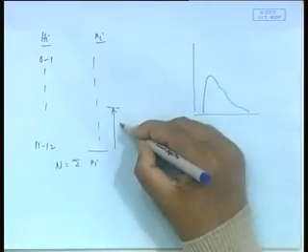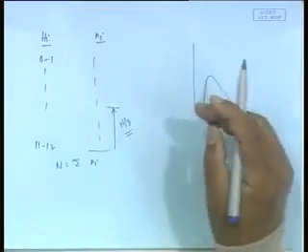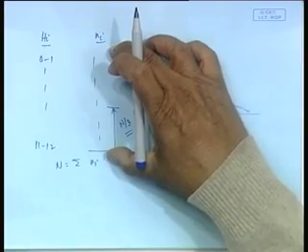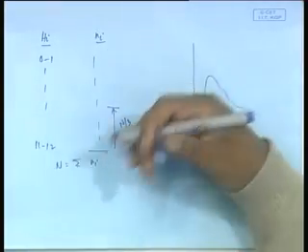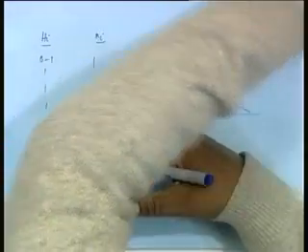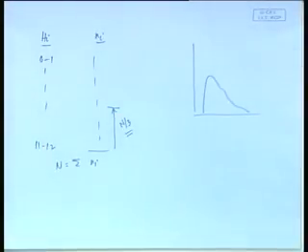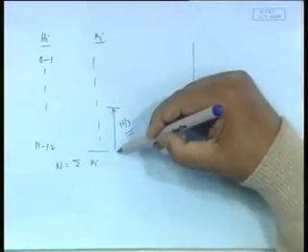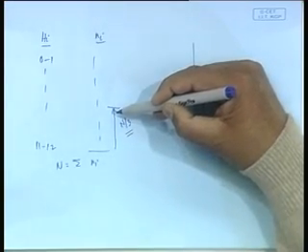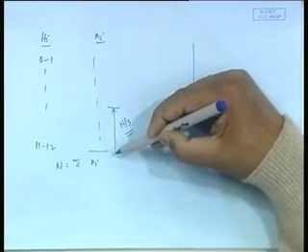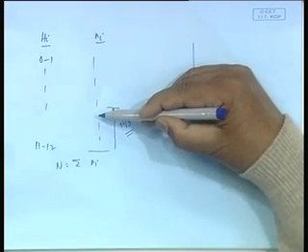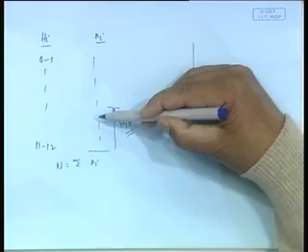number of waves, 1/3 of the data. Suppose there was 1000, total n was 1000. I will give an example of this later on, because this is very important from any point of view. So, we need to give this example. Suppose from here I take 1/3 of the total number of waves, which is, if it is 1000, say 333. Then take those waves and average it. Then I will call that the 1/3 significant wave height.